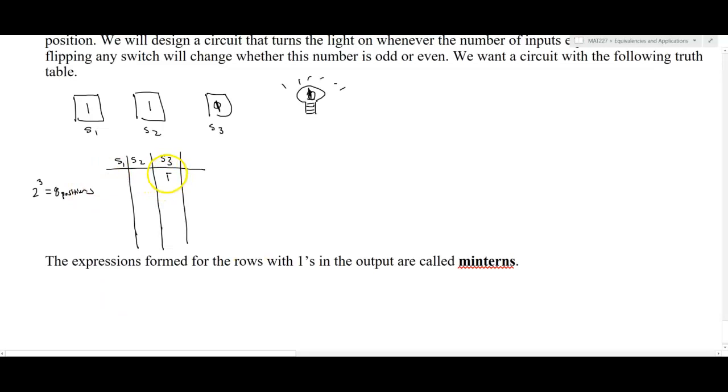And as long as you list them out as false, true, false, true, false, true, false, true, and then list this out as false, false, true, true, false, false, true, true, and this last one as 4 falses followed by 4 trues, you'll have hit every single possibility. So here is what we want the light to do. We said that as long as there's an odd number of switches on, we want the light to be on.